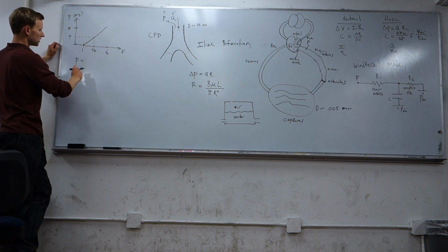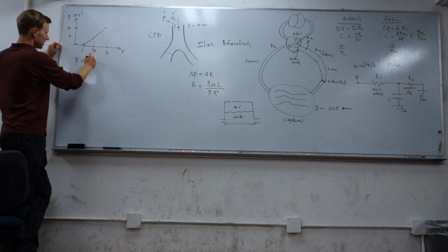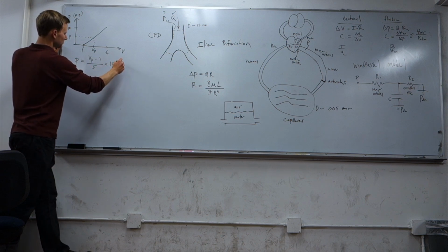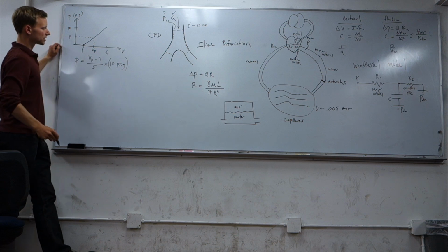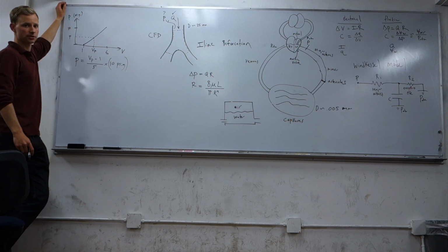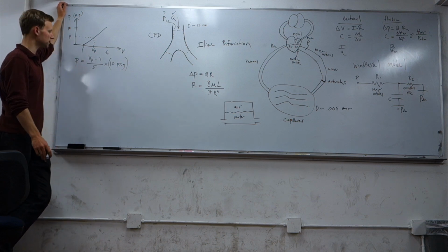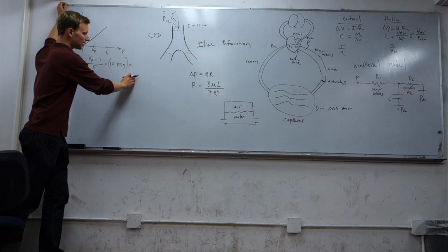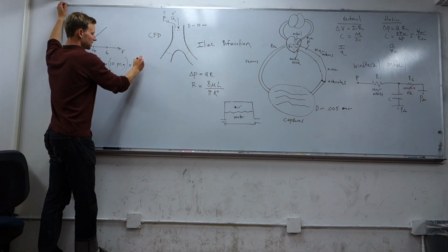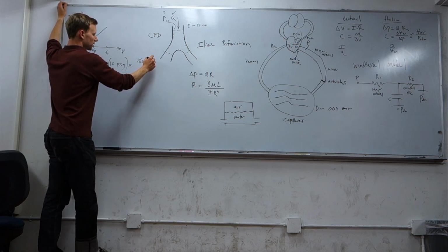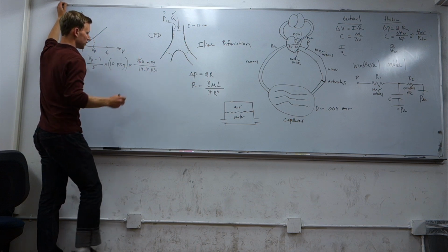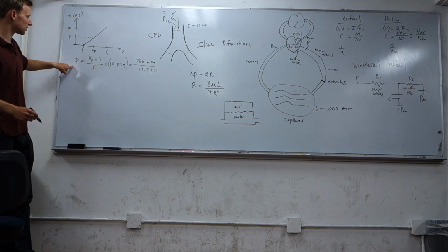P equals (Vp minus 1) over (6 minus 1), which is 5, times 10 psi. And since we're dealing with a cardiovascular system, we want our pressures in millimeters of mercury because that's the standard unit for some reason. So times the conversion from psi to millimeters of mercury. We'll use 1 atmosphere. There's 760 millimeters of mercury in 1 atmosphere, and there's also 14.7 psi in 1 atmosphere. This is the conversion from voltage to pressure. Okay? Keep that in mind.